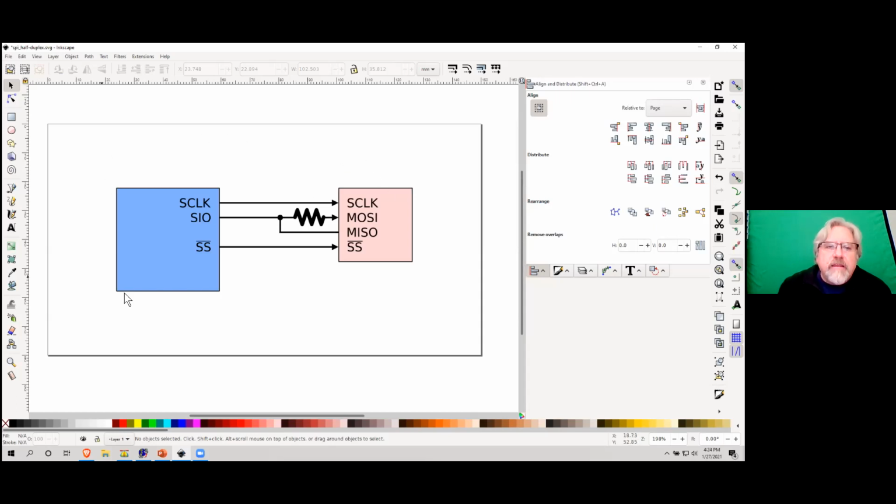But again, not really common, and with the P2, we're less constrained with IO pins. But if you do get into a pinch and you have a half duplex device like the ADC0838, which again is not needed as frequently anymore because we have ADCs built into the P2, this is a solution that is kind of a modified SPI.